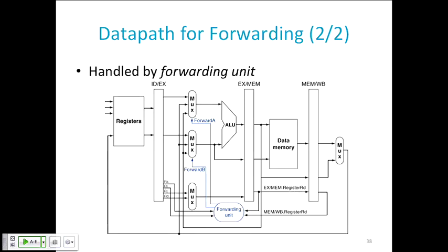And notice I can mux on either side. It can be either the RS or RT side. I can read operands on either one of those places. So I need muxes for both RS and RT to do all the forwarding.